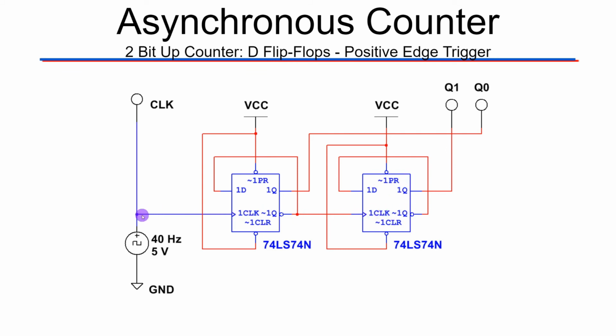And the reason that's important is we want to know that for this flip-flop to change from 1 to 0 actually requires 2 rising edges, right? The first to write the first one, and then if it changes, the second rising edge to write the second. And the importance of that is that this output is going to be half as frequent as our clock signal at every flip-flop.